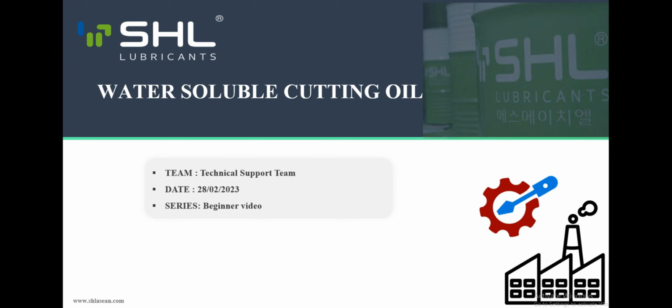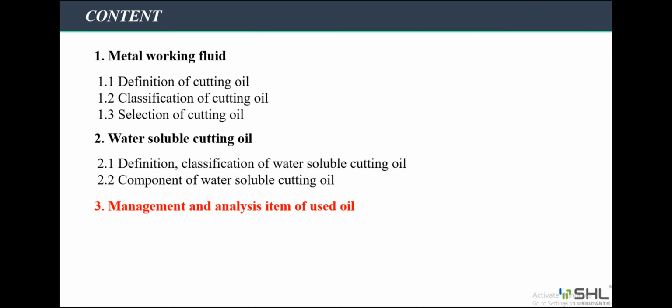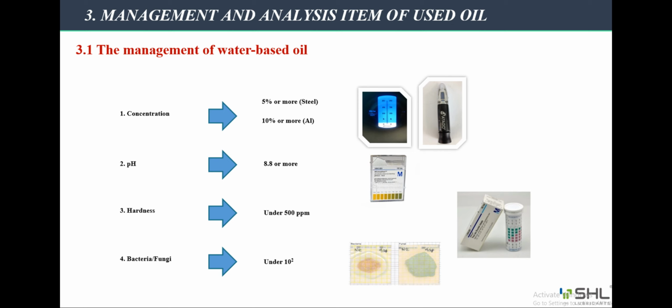In the prior part we introduced the theory of water-soluble cutting oil. Today we would like to continue to share the next part related to use and manage the oil. When using water-soluble cutting oil, we need to manage 4 factors. That is concentration, pH, hard water, bacteria.